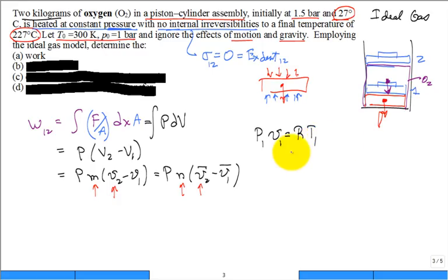And if that's on a molar basis, is P1 V1 bar equal to R bar T1? Yes or no? Do you like both of these equations? You can see where one equation works. What's the difference between this R and that R? There's a bar on one of them. Are they the same? No, they're not the same. What's the relationship between the two? The molar mass. Exactly right.